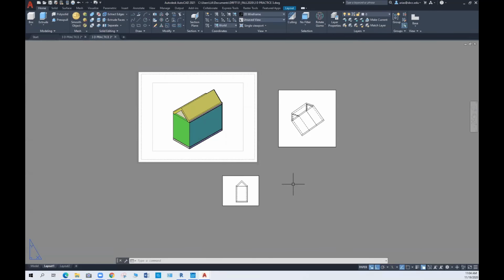And as I said before, this is kind of a turnaround from when you did the floor plan, elevations and sections in 2D and then we moved to 3D. Now we're actually going back from the 3D. We are doing plans, elevations, and sections. And as I said, you could check the accuracy of your first drawings against these ones now that these are extracted from the 3D view.